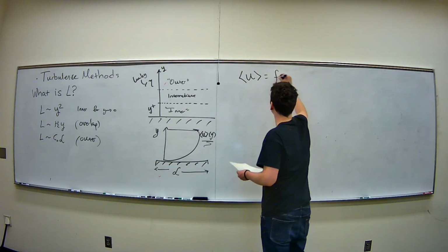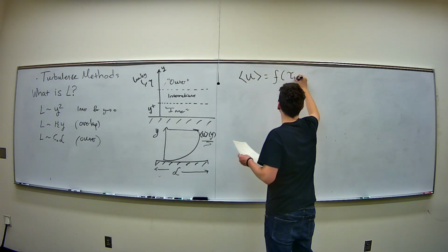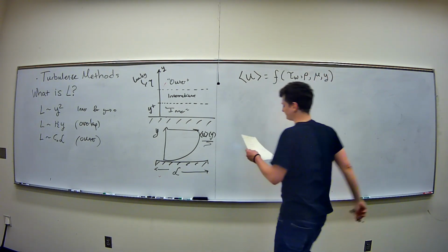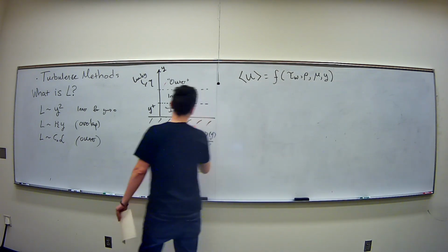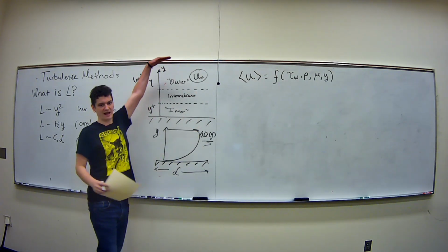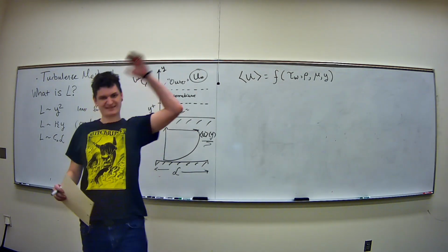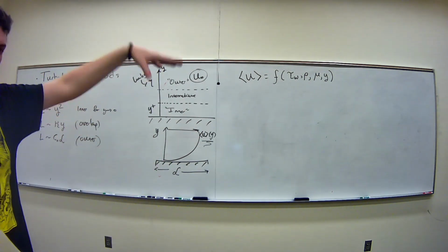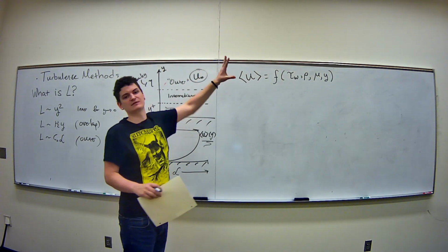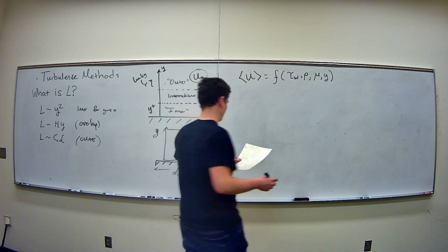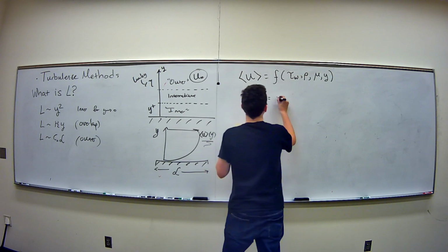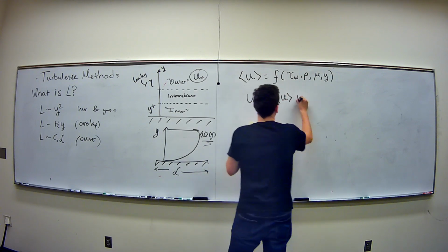Okay, so this is going to be, assume just some educated guessing that you have enough variables. And then you have up here, outer wall is this u infinity. Okay, so this outer wall with that situation just on boundary layers, it still holds for turbulent flow, where the very far outflow is just this u naught, or at least the scale of that flow is certainly most of it going at this u infinity or outer velocity. Okay, so then you have another functional relationship: what's this outer one? And that you would assume to be this.